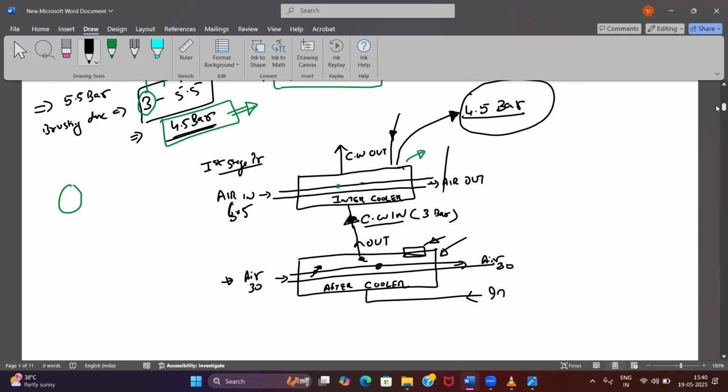Sir, he's asking, like, the bursting disc was there, so the tubes got leaked, but the air is going with the jacket water outlet. So in the time period you're leaking, you don't know, but it's still leaking. So how can you know that the air is going with the jacket water outlet? The bursting disc won't burst, so what will you do? The bursting disc will not burst and air is going with the jacket water outlet. Sir, you can see bubbles in the expansion tank. The expansion tank is a later thing.